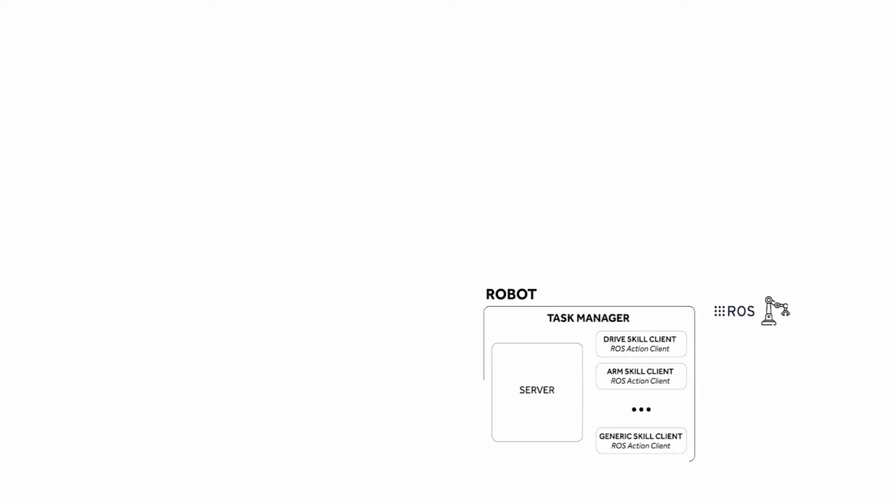Inside each of INESC TEC's robots, there's an instance of the Task Manager running. Task Manager is a ROS package responsible for orchestrating the execution of robotic tasks. Each robotic task consists of a sequence of robotic skills. Robotic skills are modular and reusable blocks of software built upon ROS actions, able to perform well-defined operations like drive operations.